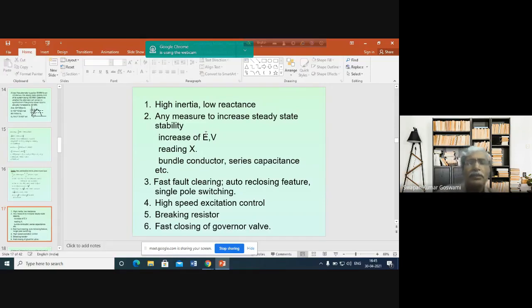As a result, the peak of the power angle curve will also fall. So we shall not allow that. Rather, we shall be adjusting the field current. We shall be varying the induced EMF. As a result of variation of field current, induced EMF will vary. So we shall be varying the induced EMF such that the terminal voltage remains constant.